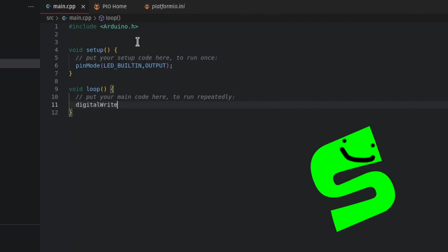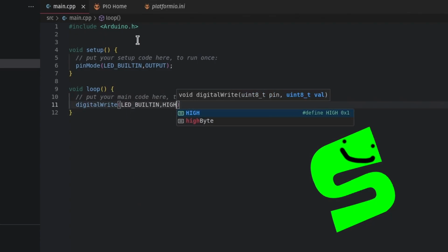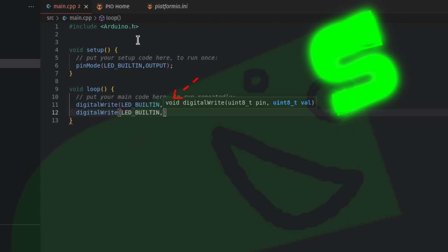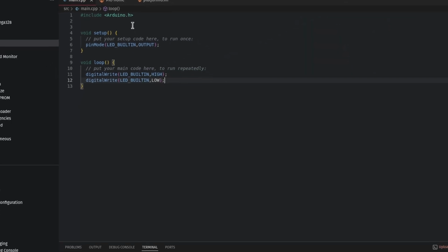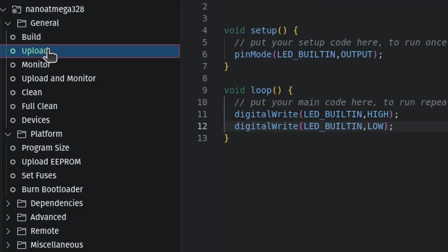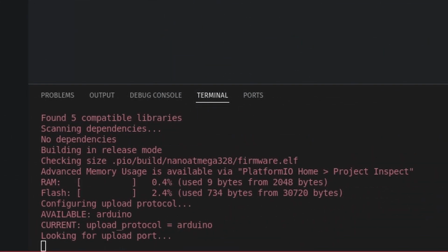Because we have the positive of the LED connected to the Arduino, to turn it on, we put it on a high state, and to turn it off, we put it on a low state. And with that, it should all be set. So we build it, and then upload it, and...